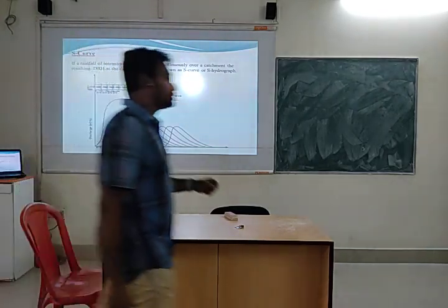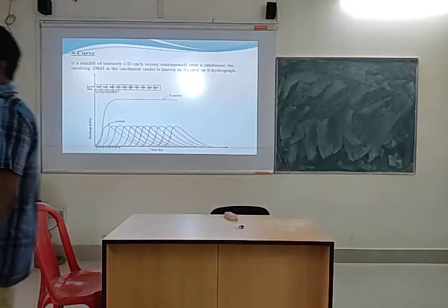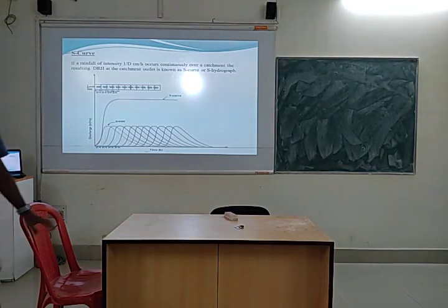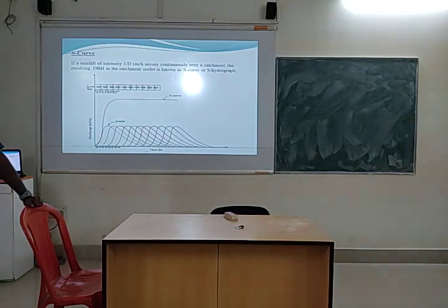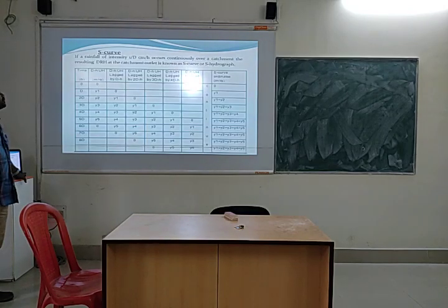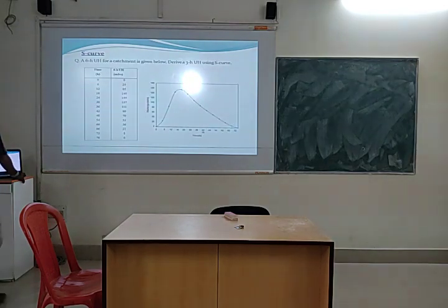We were discussing this S curve, and we have done one example as well, right? That example was pretty easy, and that is why I have asked about another example, which is for non-integer multiples, like a 6 hour precipitation. A 6 hour duration of unit hydrograph was given in this example, and they have asked to find out the 3 hour unit hydrograph, and I have asked you to go through this.